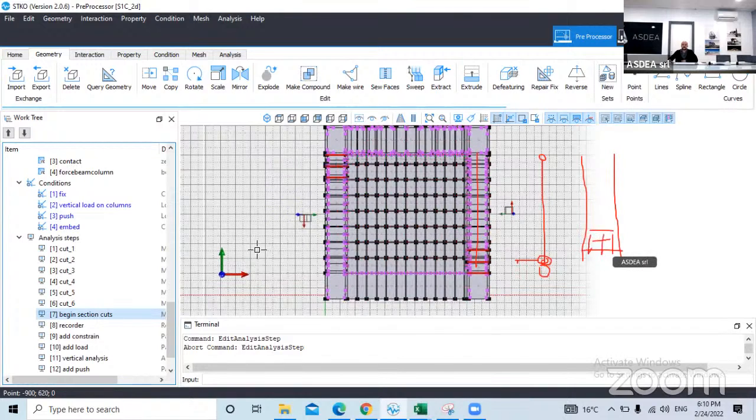Now, when you have continuum elements, either 2D or 3D, you cannot directly measure the entire shear that you have at a certain point. What you can visualize is the shear stress, or any other stress in the other direction, but you don't have the total shear. You can visualize it, for example, if you have a fixity at the bottom. Here you can visualize the total base shear because it is the opposite of the sum of the reaction forces. But if you want to measure the shear in between in your model, you cannot do that.